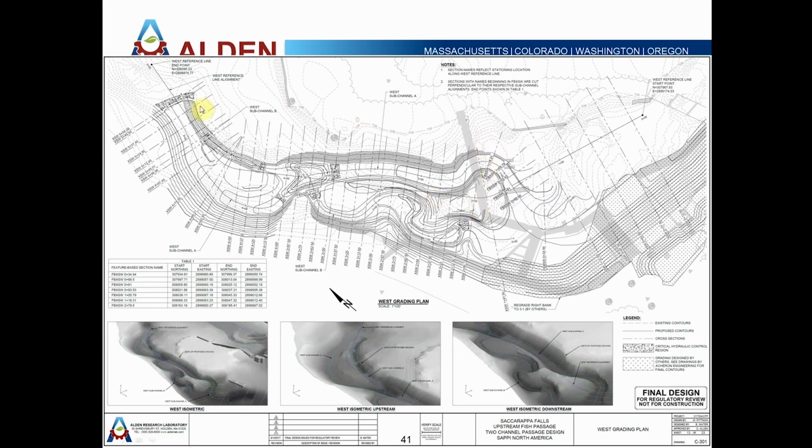So we had to come up with construction plans to bid on. And we did the traditional approach of having lots of alignments and cross sections all over the place to try to capture this design. One of the things we really wanted to focus on was hydraulic control points, that we wanted to make sure the contractor kept those within a tighter tolerance to maintain the hydraulic grade line through here and maintain our pools.